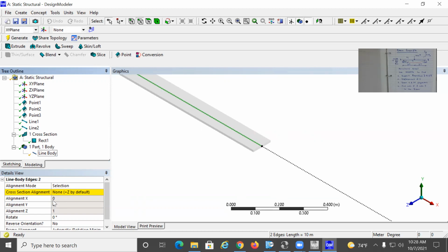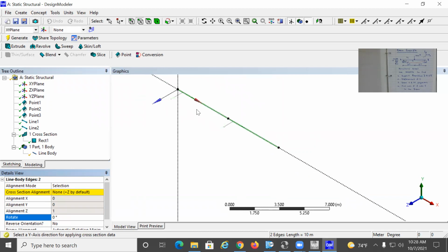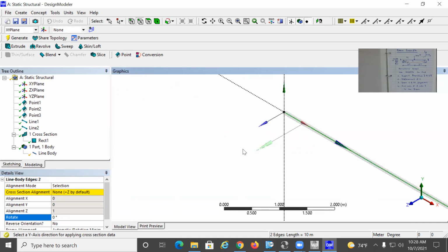Okay. Now there are two ways we can do this. I can choose to rotate my section 90 degrees or minus 90 degrees. So I can come here and give it a rotation. Like I can go minus 90 degrees. This will fix it. I can even do a 90 degree. I'll get the same effect. If I take it back to 0, this is where we started. My y-axis is aligned along my z. You see the y-axis of the section aligned along the z.